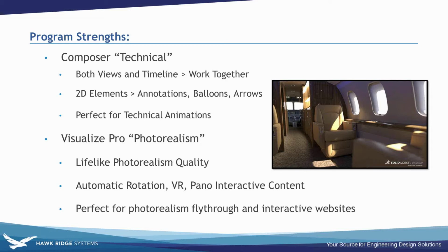Where the strengths are in Visualize is a lot of the automatic content you get out of that. So you import your model from SOLIDWORKS or from wherever you want to import that from. Actually, the one I'm using today is a step file. I'm not even sure what program made it. If you bring anything in, you can set your scenes, set your materials, and then you say, hey, I want a VR rotatable model.